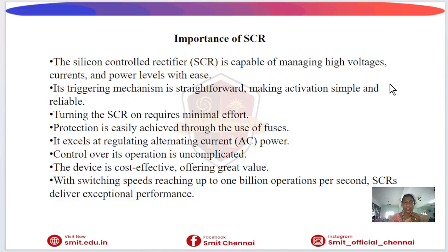Now the importance of SCR, why the SCR is so popular. It is a common apparatus that handles high power. It can withstand high voltage and high current, and it can be triggered easily, since only a small gate signal is required. Next is fast switching, a very quick response with reliable operation. It is used extensively in industry and is cost effective, with low cost compared with many switching devices. Efficient power control is also possible, and it is excellent for AC power regulation.